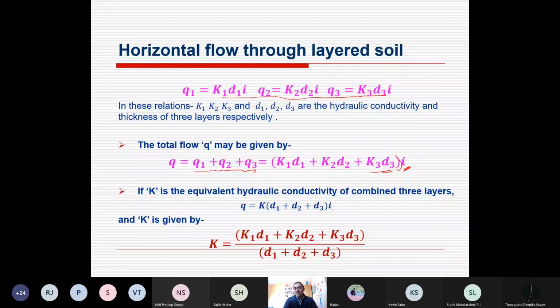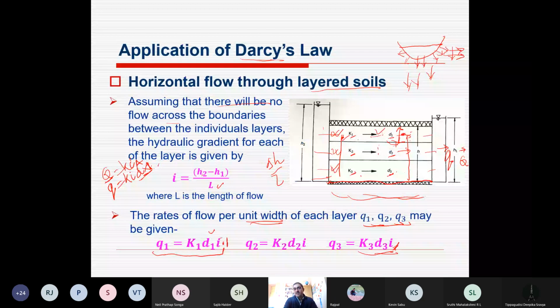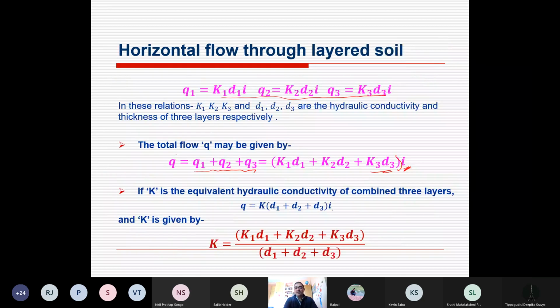Reason being, inflow has a constant head condition, and outflow we consider as a constant head condition for all 3 layers as a single outlet condition. In this way we have the equivalent discharge Q, adding up the hydraulic conductivity based flow of all 3 layers.